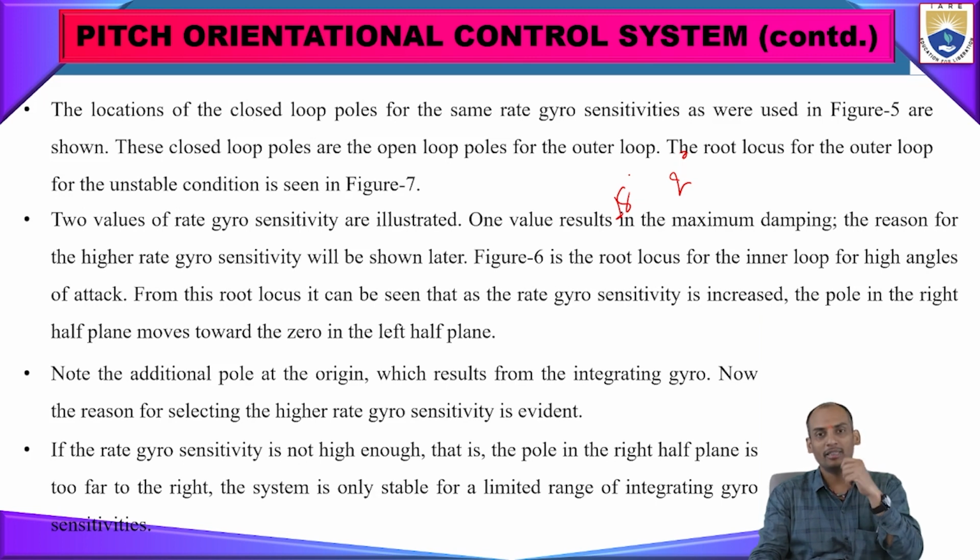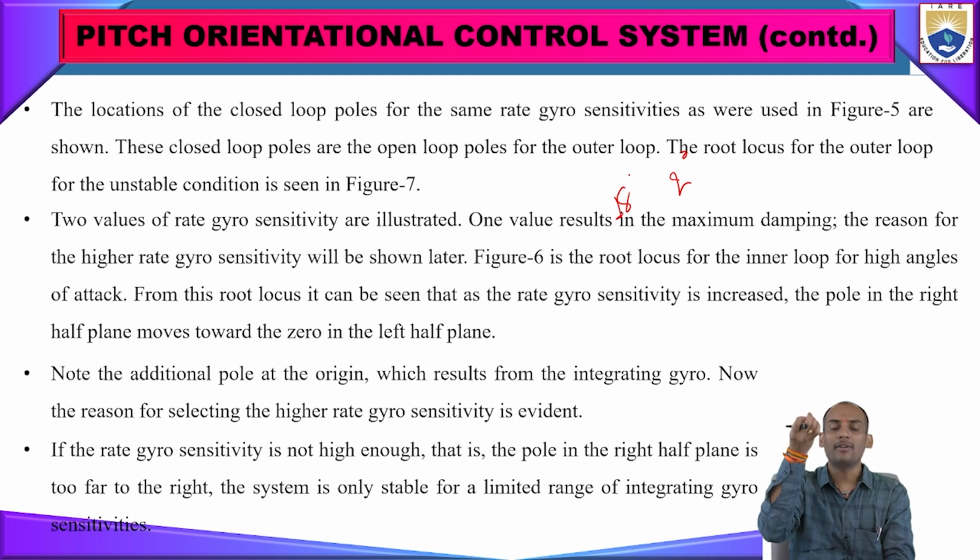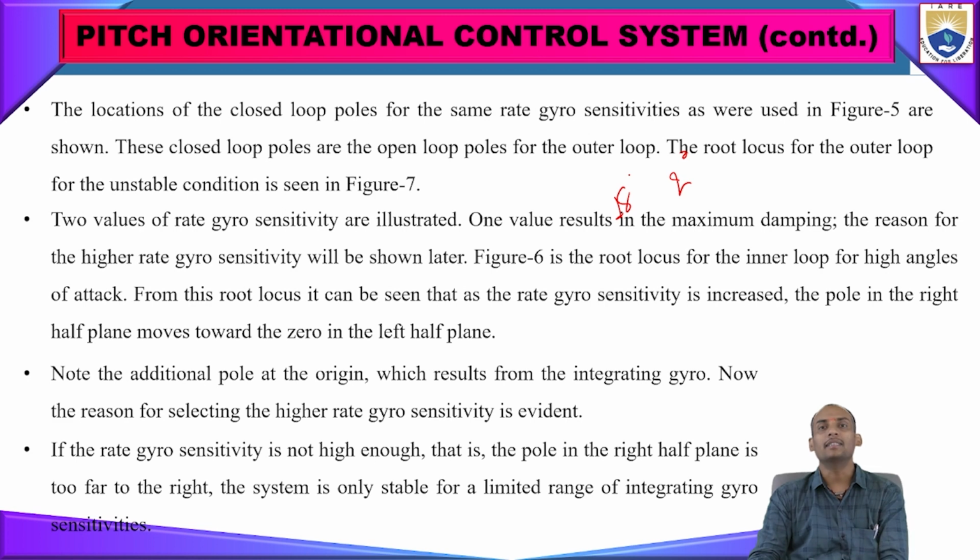Okay, so whenever we apply forces on the control stick, the rate gyro senses that correctly through the amplifier, and the gyro system also gets the values very rapidly, so that feel is given to the pilot. Whenever it is achieving the critical value, it will cut the signal before that. That is how the rate gyro sensor is designed.